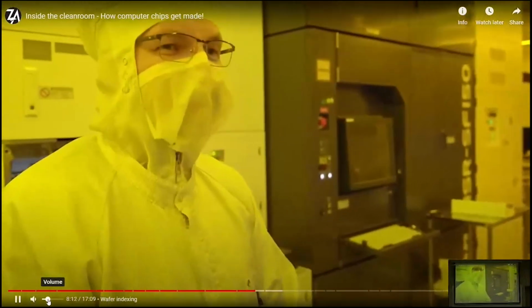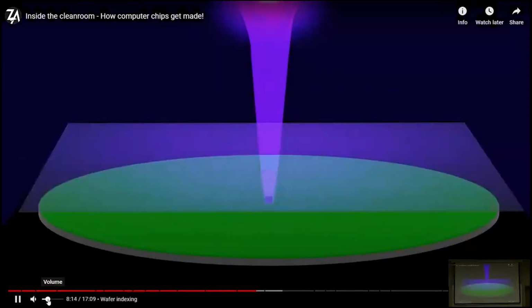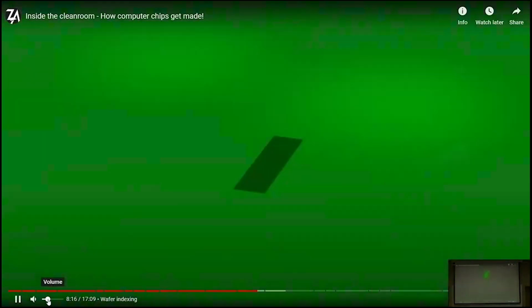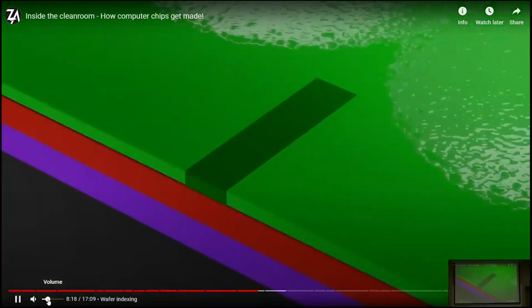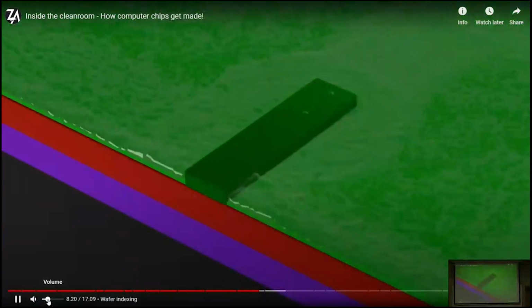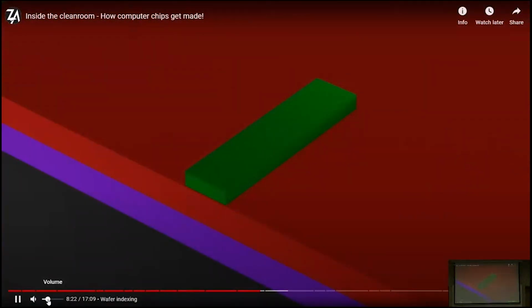Yeah, okay. After the photoresist is exposed to light, it changes its structure, and then we can develop it so we can remove the exposed regions. Once we have the patterns, the photoresist acts as a mask, and we can do the etching then. So to etch our deep trenches, for example.